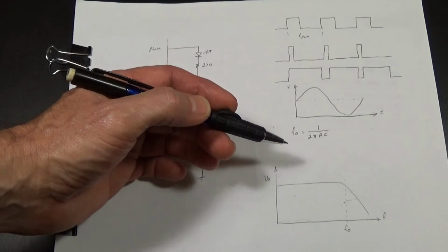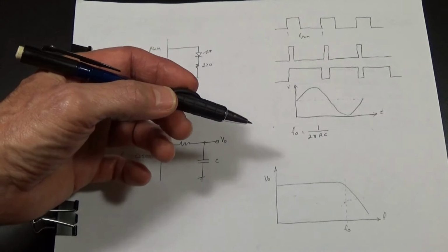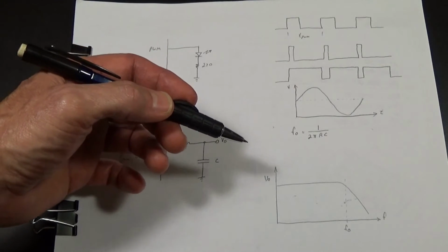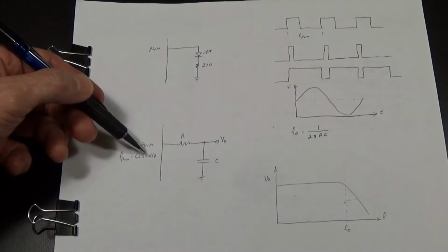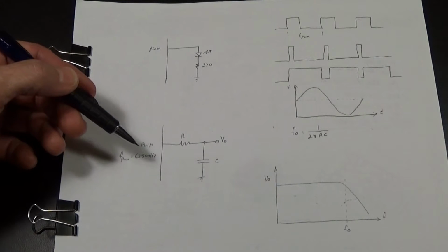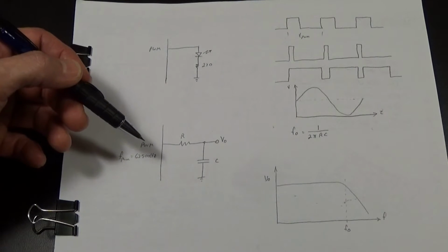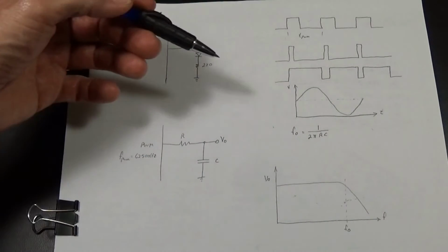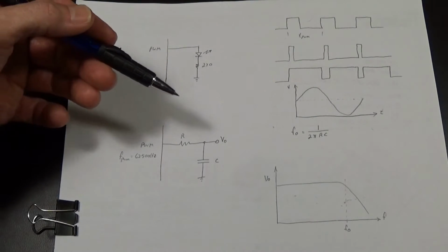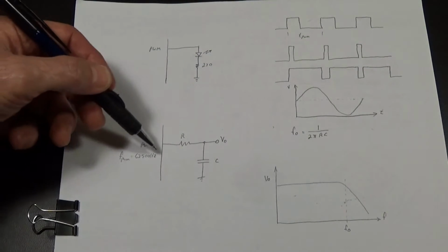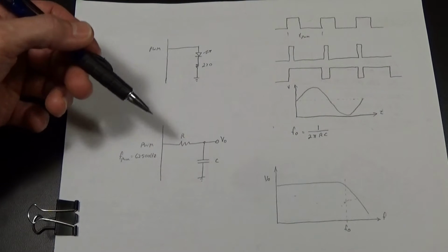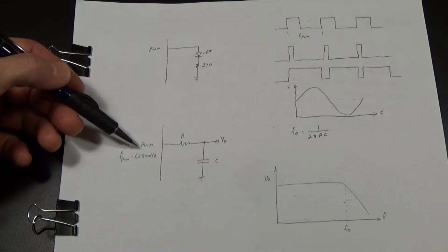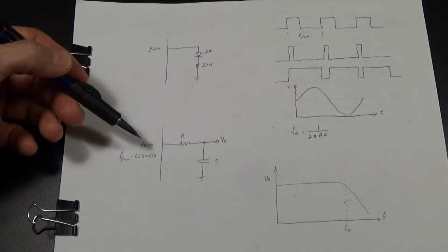And we increment that counter at a fixed rate. In my example here I chose 50 kilohertz as a fixed rate. It's less than this frequency, but really the two frequencies don't have anything to do with each other. The 50 kilohertz is just how often I update the changes in the duty cycle in my PWM. So it's completely unrelated to the 62.5 kilohertz of the PWM frequency. Although, like I said, this limits the highest frequency you can actually generate.